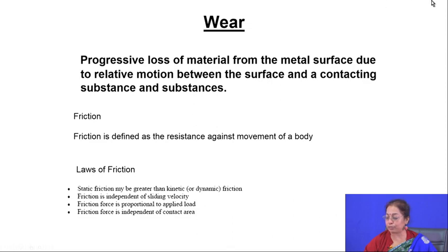The difference between wear failure and failure due to compressive and tensile loading is as follows. In wear, there is always relative motion between the two surfaces, but in other modes of failure like compressive failure, both the components are static in nature. As a result, when a component fails by compressive loading, the failure occurs very quickly, but wear failure occurs in a much slower fashion. It is progressive in nature and it is very much controllable.